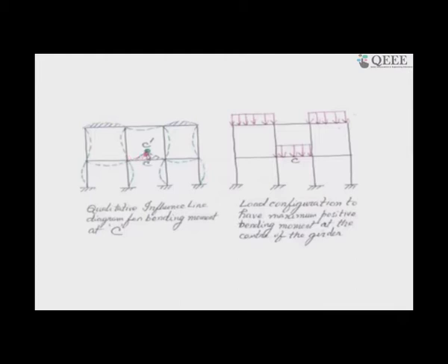At the beam-column junction, the whole thing needs to rotate, and that is what it has done. So, its column has been tilted, its beam has been tilted down on one side, and this beam has gone up. To do that, it will have a deflected shape like this, and it will also bend the column there. Of course, we are drawing it in an exaggerated manner.